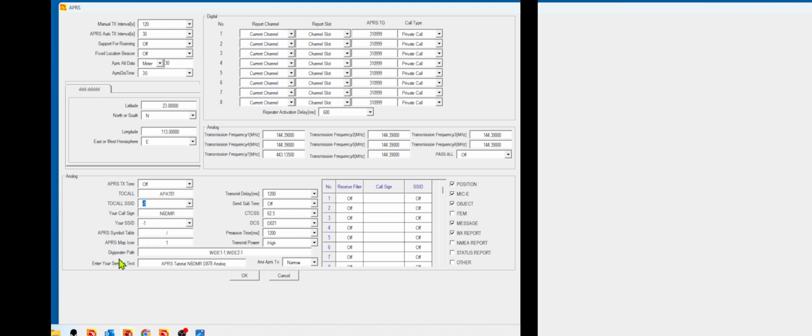All right, next thing you need to set is the digipeater path. Now, receiving APRS signals in the United States, there are two types of receivers. One is an iGate, which does nothing but receive, and it will not pass or bounce your signals anywhere else. It will receive it, and if it is connected to the internet, it will post your packet on APRS.fi the way you're supposed to, and your location will show up.